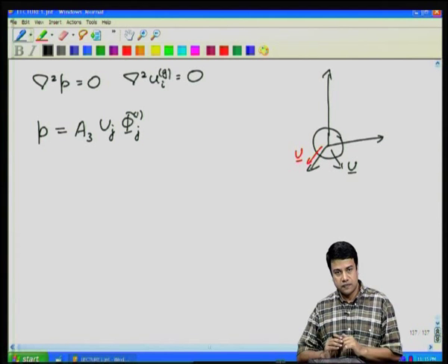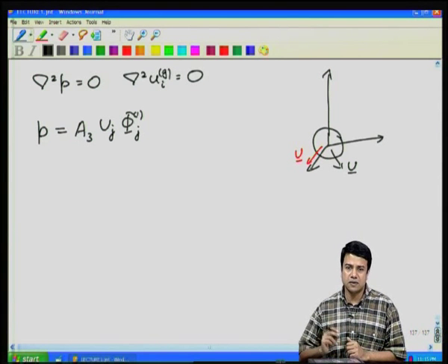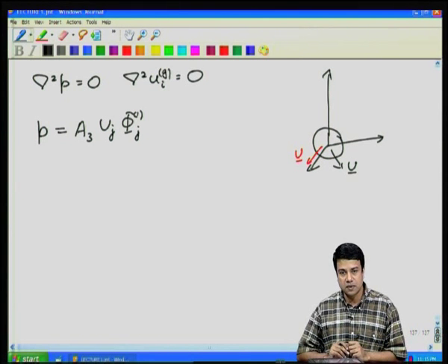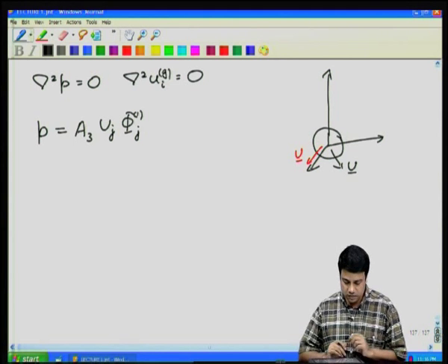Okay. If I multiply this by a scalar, I will get a vector, and pressure is a scalar, so it cannot be that. If I dot this with a second, third, higher order tensor, I will get something that is not a scalar. So, the only possible combination which was linear in u as well as linear in one of the spherical harmonics is this one, the vector u dotted with the first solution, the dipole solution. Okay.